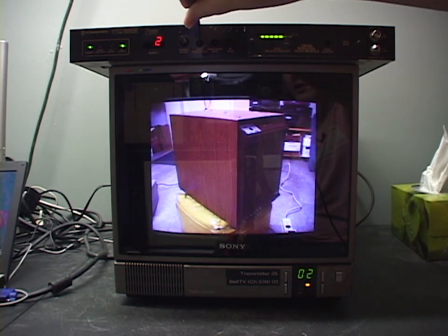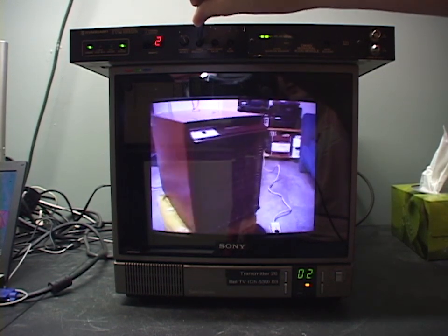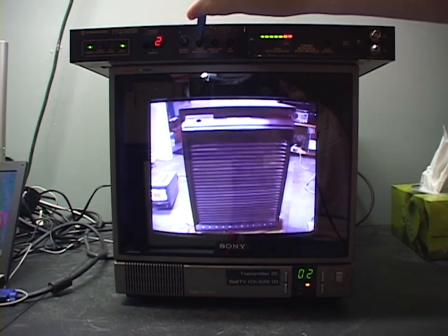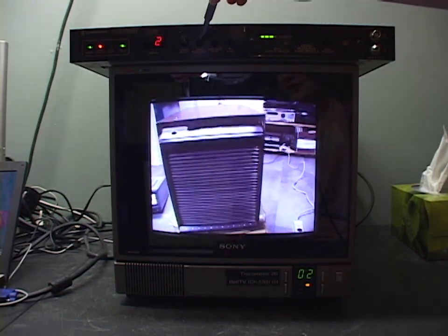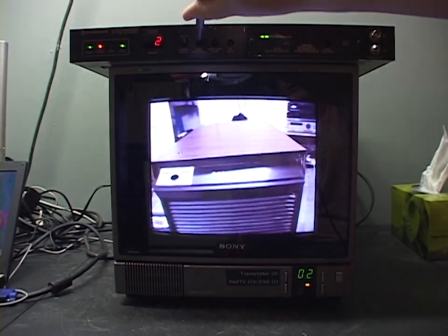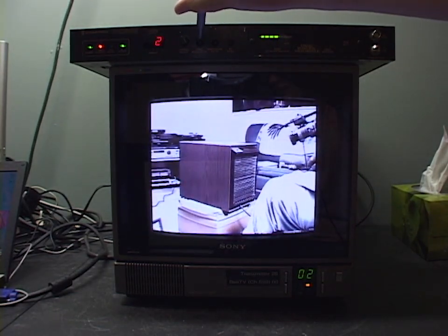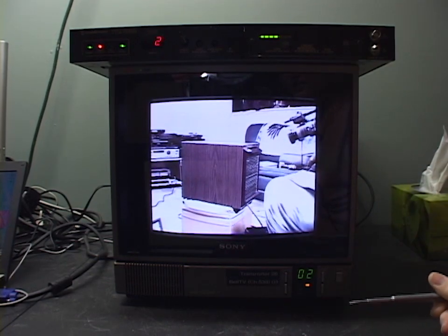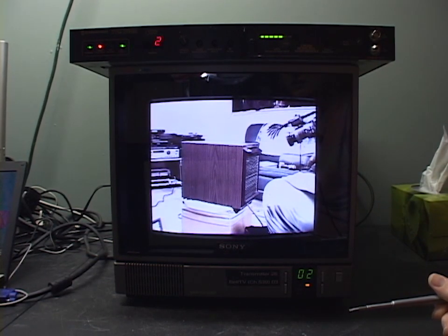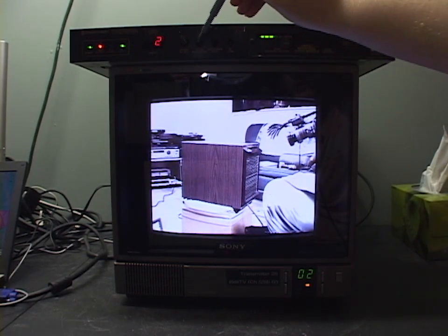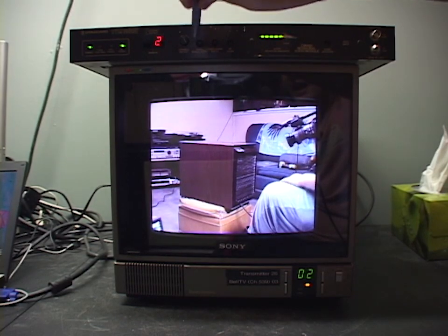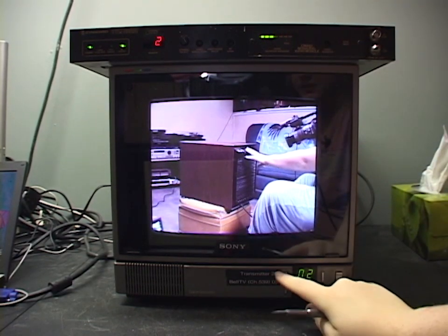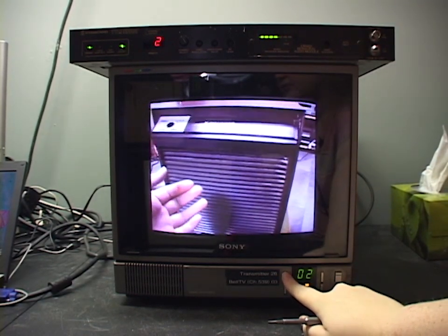And if your video modulation is too high, a couple of things happen. Well, first, that overmodulation LED lights up, but you can also see the video becomes too bright, and things become very white, and it loses dynamic range, and everything is just blown out. But there's something else that happens if your video is overmodulated too. I'll turn the volume up here.